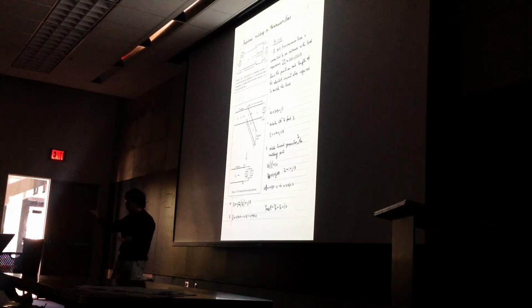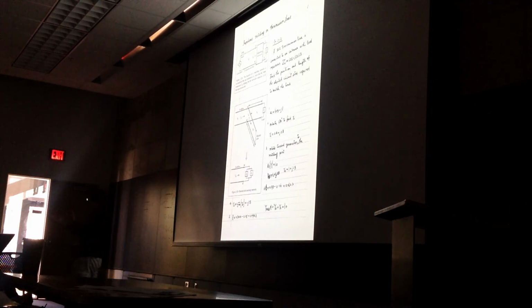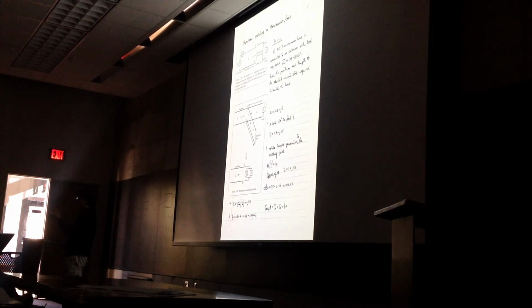At a given frequency. The inductor you keep talking about is at DC, so it makes sense to think of it that way. But now you are talking about an inductor at 1 gigahertz, and that's slightly different. This kind of wire at 1 gigahertz may not be the same 10 to the minus 8 Henry as you expect.